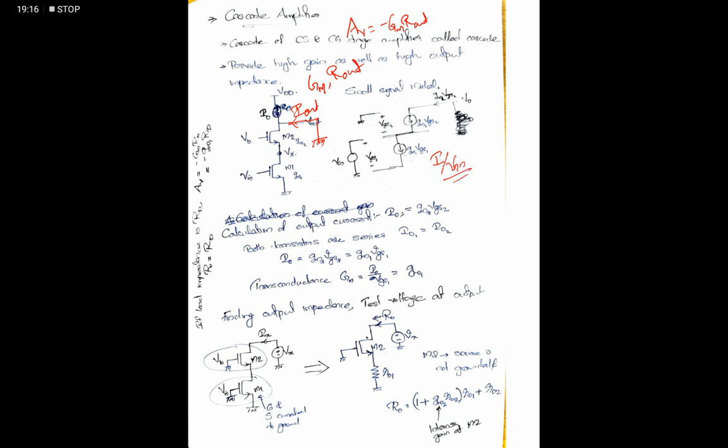will be the transconductance of that MOSFET. For that, here we grounded the output, and this is the small signal equivalent of the grounded configuration. Then these two are connected in series. This one is shorted to ground. Here the bottom MOSFET indicates M1 and the top one indicates M2.